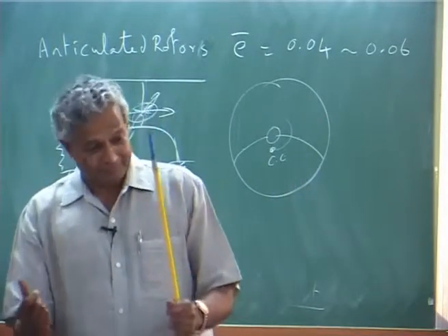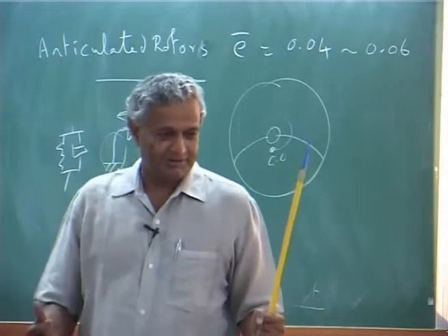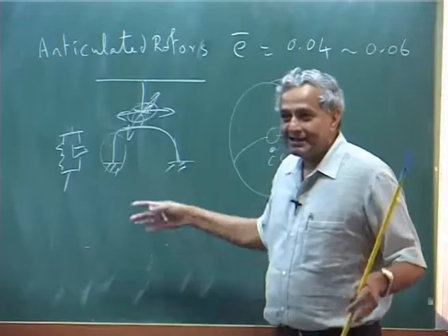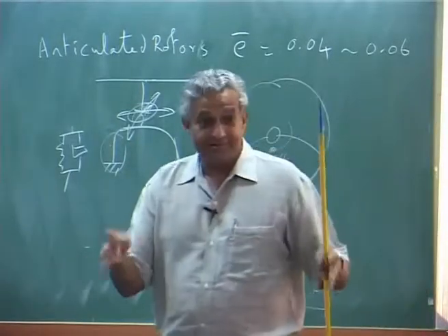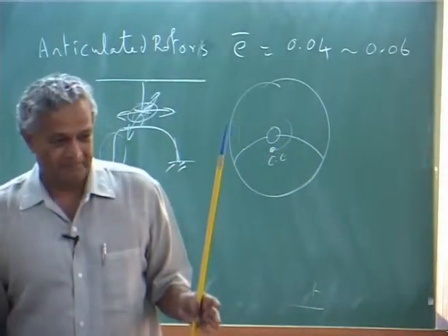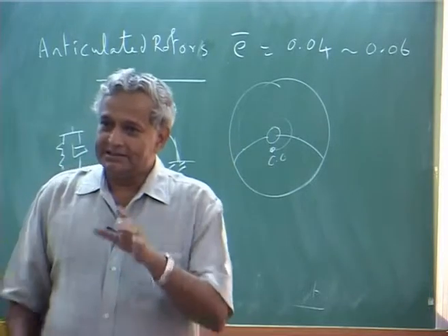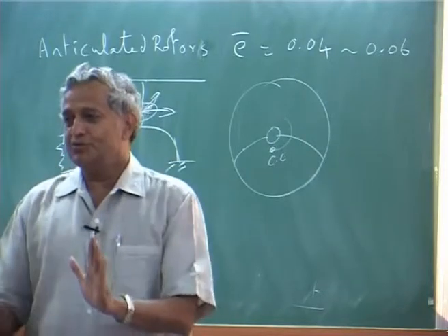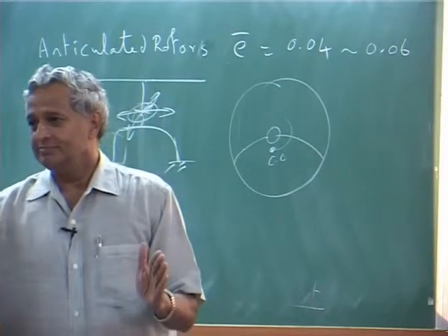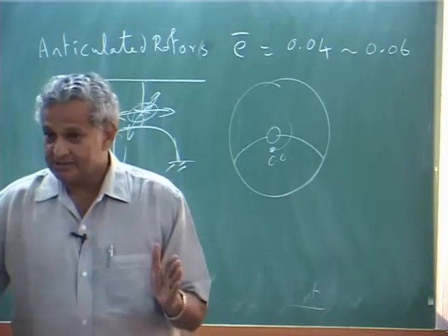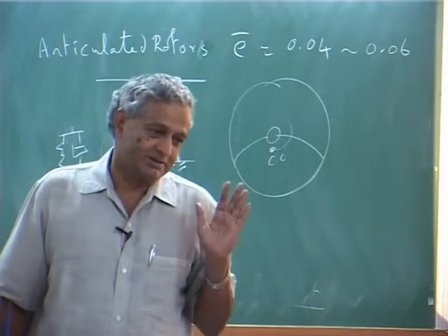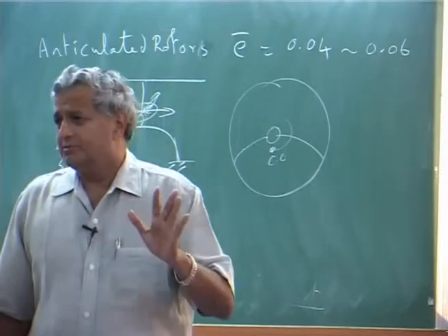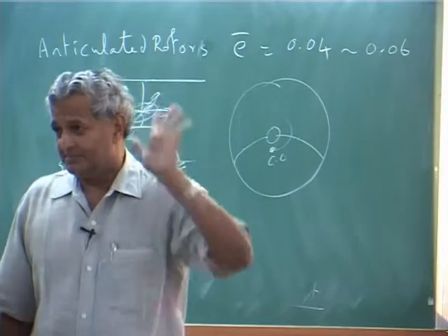The wheel type, yes, they had some problems initially, and then they had to put in a damper and increase the damping. Tire pressure, everything matches. It should be very, very critical. So the analysis you do, finally make sure that during your operational range you don't get into a ground resonance problem. And one of the ways to avoid it is to put in dampers.